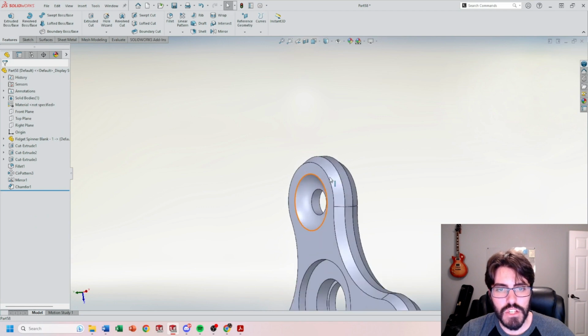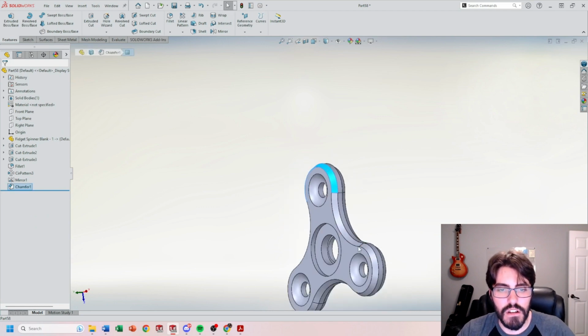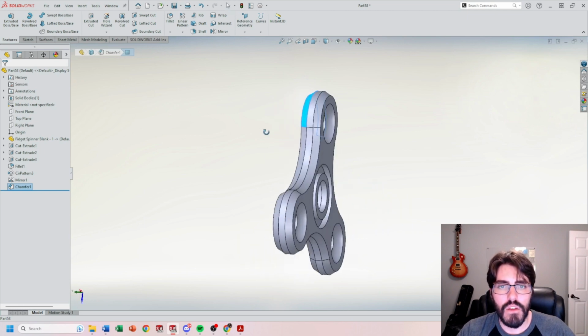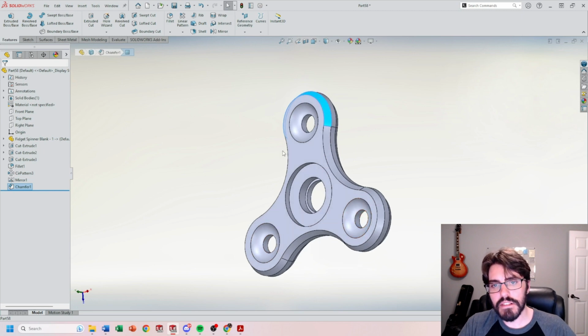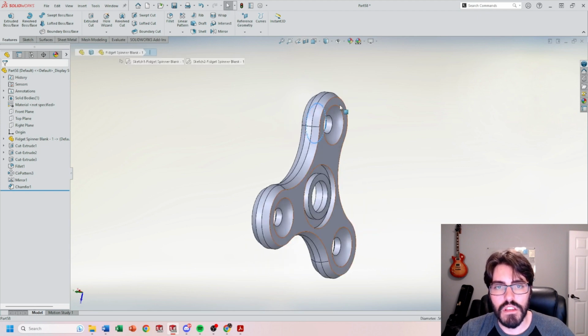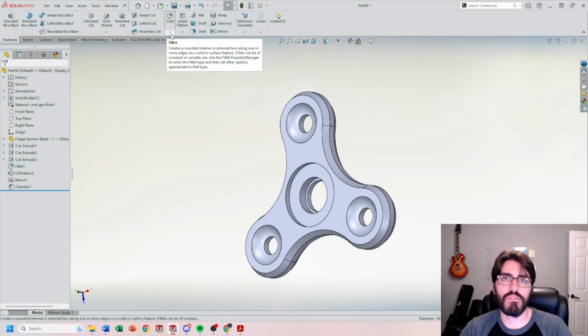All right, so now we have a 30 degree edge break that we'll eventually have to do a 5-axis continuous or simultaneous swarf on. And we have our details here with the reveals. So the last thing that I want to talk about here is actually the edge breaks on each one of these reveals. Now, I'm not saying that they're typically going to be super sharp and that we have to break them, or that we should add an edge break, but more from a stylistic or a design point of view, I want to show you 2 ways of how you could approach this.